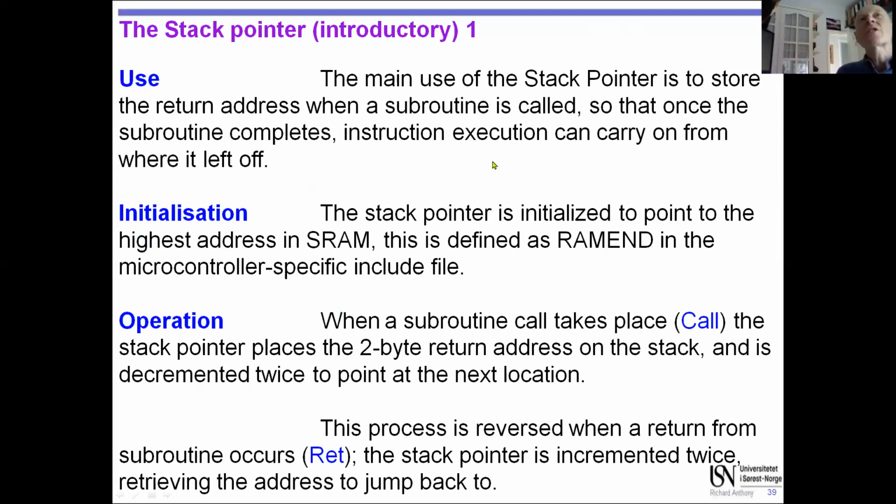Stack pointer, so these are the last couple of slides, then we've got some other little bits and pieces to talk about quickly. So the stack pointer, as I mentioned before, we use it to remember where we are in a program execution, all right? So basically, if you have a subroutine call, or you have a function call in a C program, the flow of operation is going to move to that subroutine. But when you get to the end of it and you return, the return instruction says go back to where you were and carry on from there.